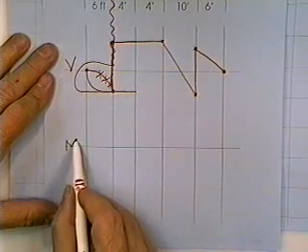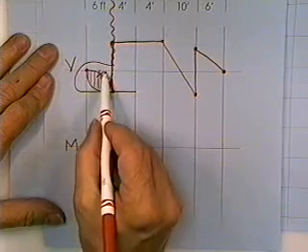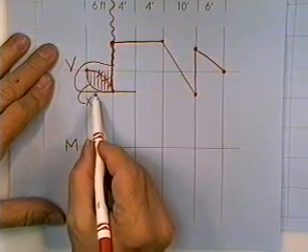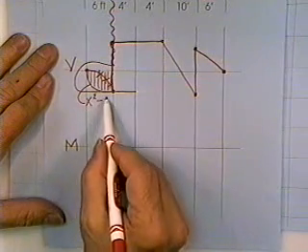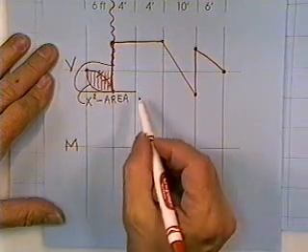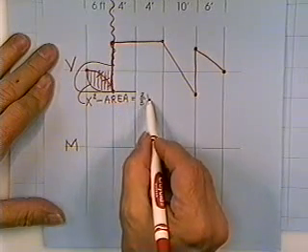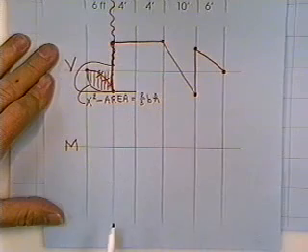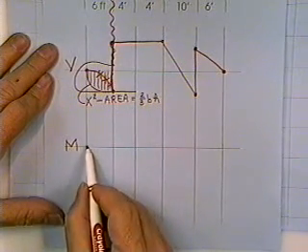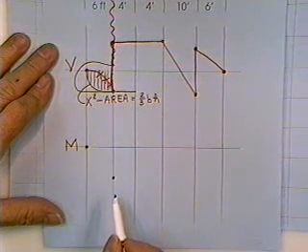Next diagram would be your moment diagram. This is the area that we're going to use. Because the power of the curve is an x squared curve, the area under that curve, if you go back on the first day and pull your notes, you'll find the area is 2/3 the base times the height. That's the area under a fat parabola. That will drive the diagram down because it's below the line.